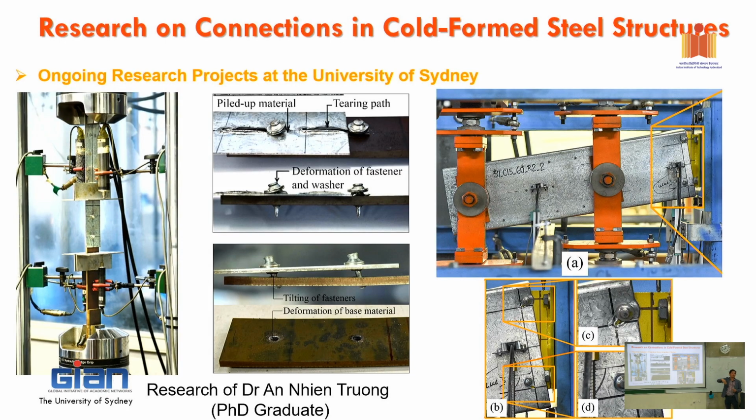And then you back calculate the shear capacity of one screw and two screws in bearing or whatever, and then you take this load divided by that, and you know how many screws you want. Okay, that's how you work it out. But in practice, the screw here is not subjected to just one single action. You can see there is a lot of rotation and a lot of shear, so it might reduce the capacity. We don't know.